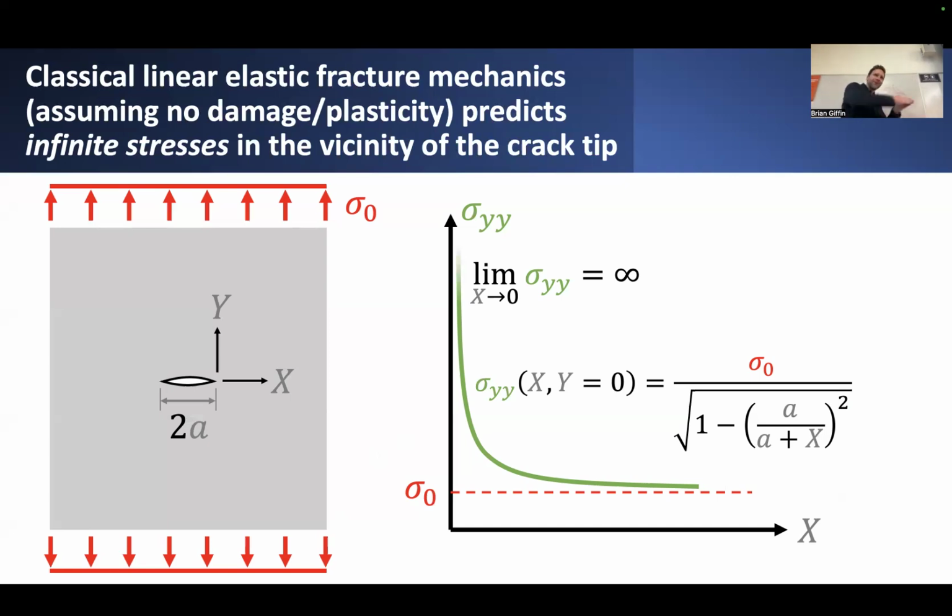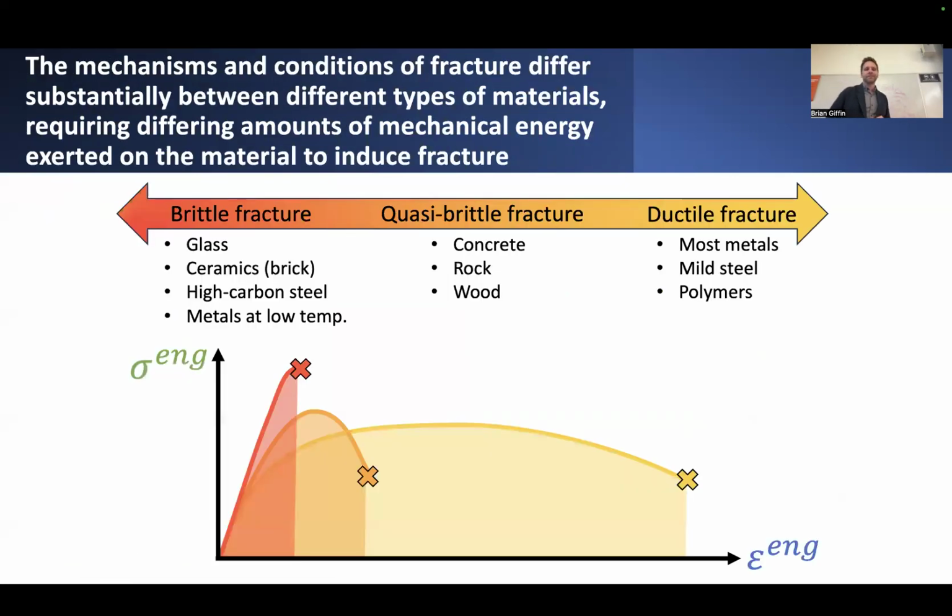In order to grow the crack, we need to have dumped enough energy into this specimen, into this local fracture process zone at the crack tip location, for enough damage to have accumulated for the crack to grow. So these are things to bear in mind from a mechanistic standpoint; that's the way we proceed, especially in the finite element context.